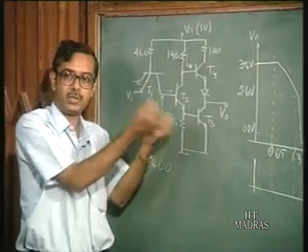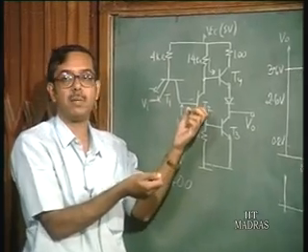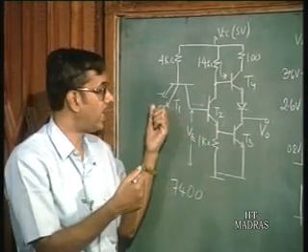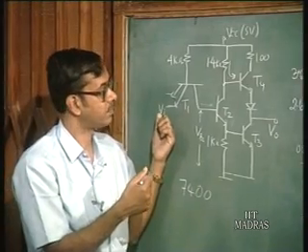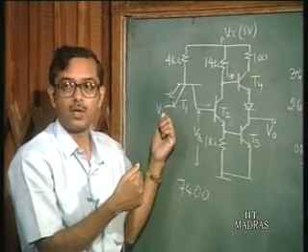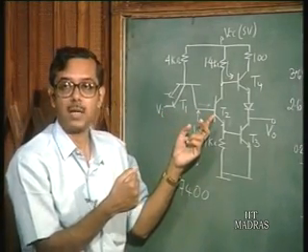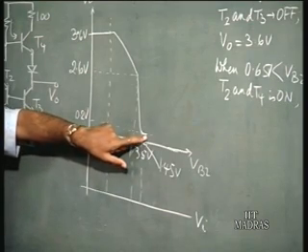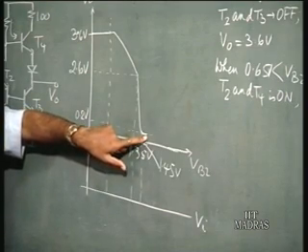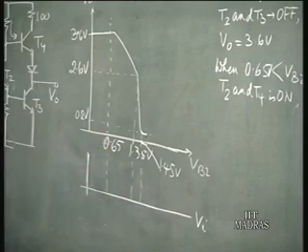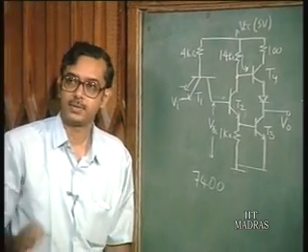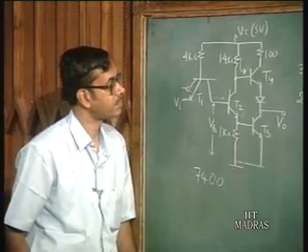So when you reduce the voltage, T2 will come out of saturation first, and then T3. So at what value of input does T2 come out of saturation? That is somewhere around this point, this 1.5, where the transistor goes to saturation. So let us look at that.